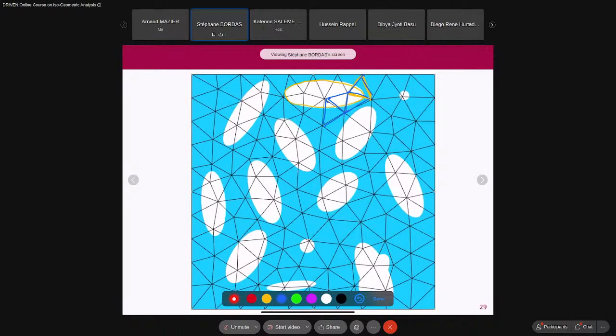We will have different cases, but what we do is we will have integration points inside through a triangulation, and integration points outside through a triangulation. The integration points inside will be associated with this Young's modulus E1, and the integration points outside, those, will be associated with Young's modulus E2, which means that you will have the ability of having two Young's moduli inside the domain.